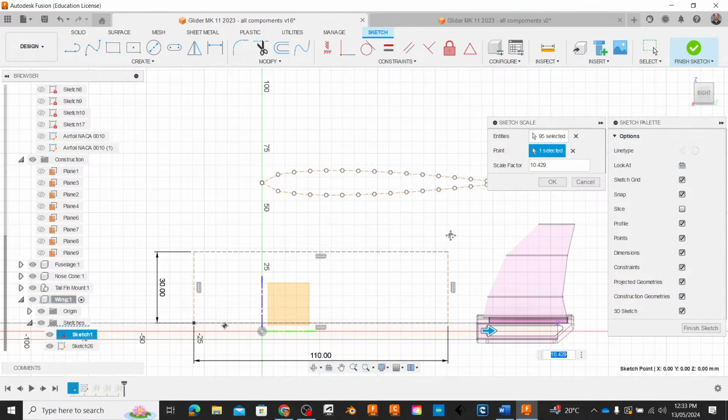And what I want is to remove all the parts of this sketch profile except for the flat portion and the top portion of the wing. You can hold down the trim tool, and it'll act like an eraser. Okay, there's a little bit of that wingtip there at the back. I'm not going to worry about that so much right now.